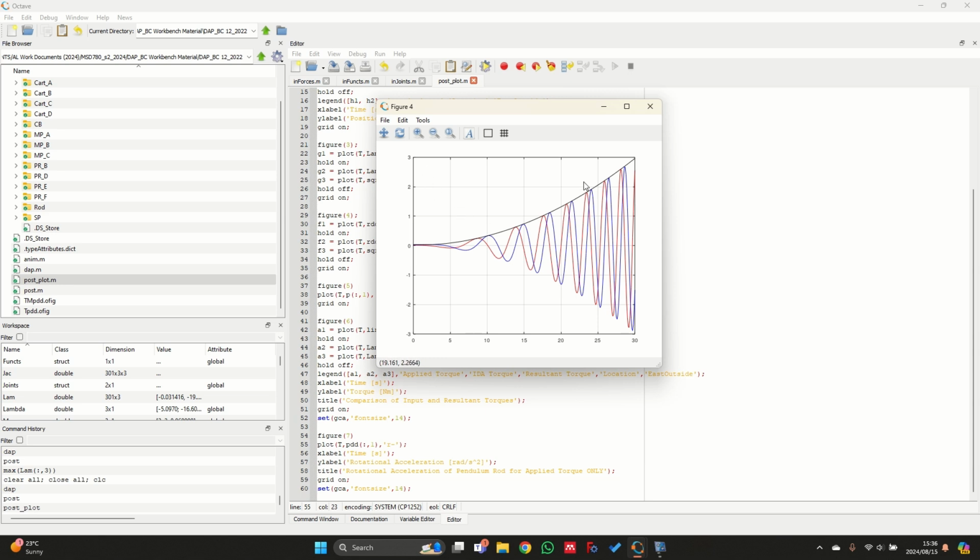In this case, we also have 3 meters per second square, so this is much smaller than the original 750 meters per second square that we had if we just specify an applied torque, so if we just specify a forward dynamic analysis. So this already tells us that there's some sort of a braking torque that is being applied to minimize this acceleration over here at the end, or to at least ensure that the acceleration is as what we had for the inverse dynamic problem.